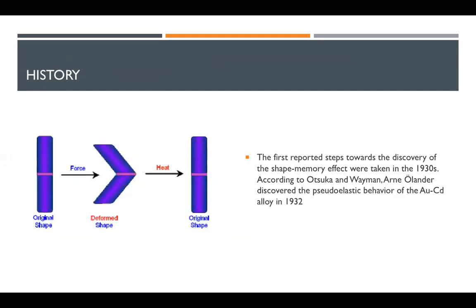The first documented material with shape memory effect was a gold cadmium alloy in 1932, but the man who really ignited the spark was W.J. Buehler, who discovered the effect in a nickel titanium alloy in 1962. This discovery led to a boom in international research in the field and the appearance of the first real applications of these alloys. Up to this day, the nickel titanium alloys are leading the industrial market, but the main drawback of these alloys for their application in civil engineering is the cost of production.